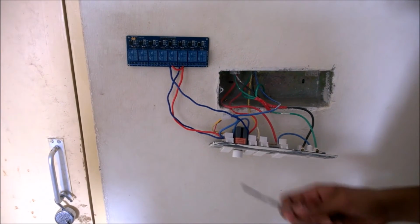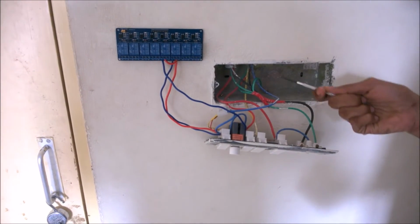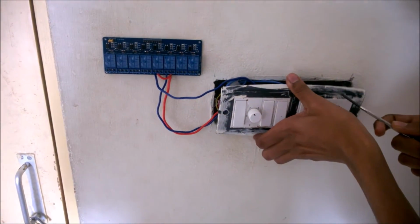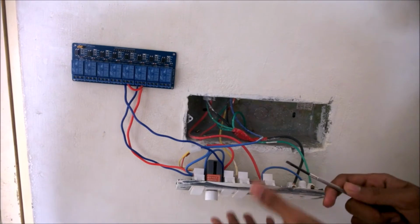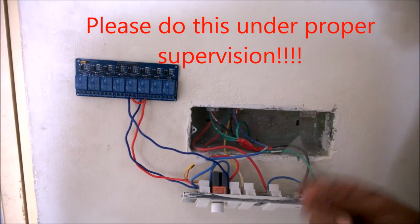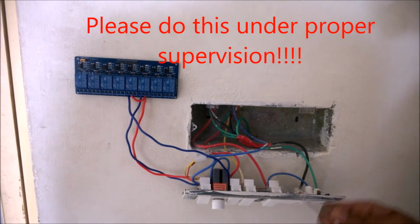Okay, let us see how we connect the relay module to the actual electric line. For that, you have to remove this switchboard, and before doing that, you have to go and switch off the main. Switch off the main. That is mandatory for your own safety.